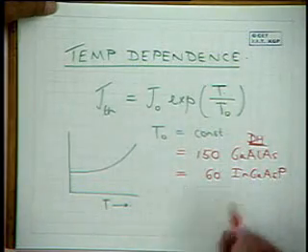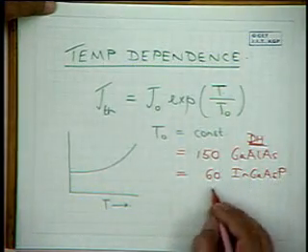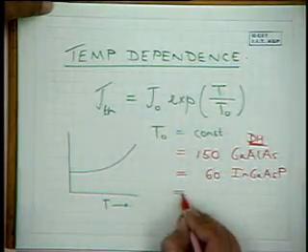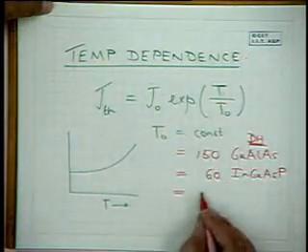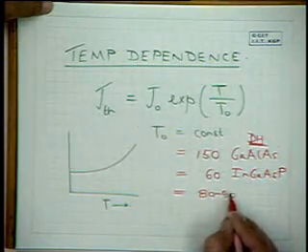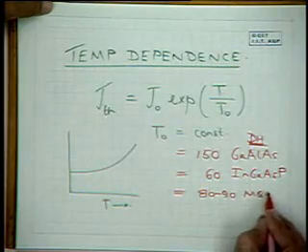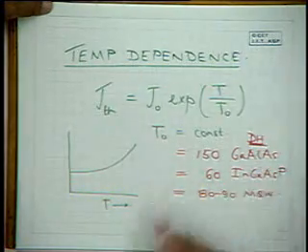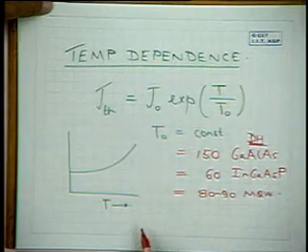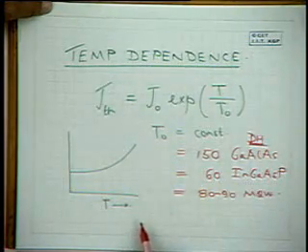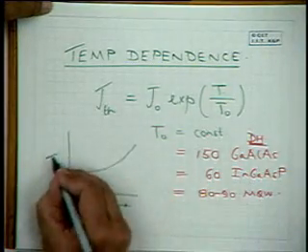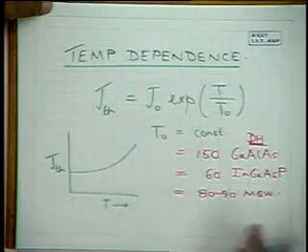One of the advantages of quantum well lasers, etc., is that for the same system working at 1.3, 1.5 microns, this value of T0 is of the order of about 80 to 90 for multi-quantum well lasers. So that is another advantage of having quantum well structures rather than common double heterojunction structures. This is J_TH, this is T.